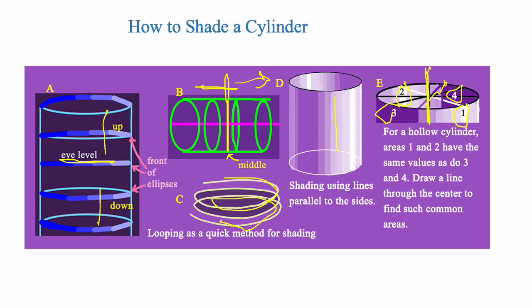To cross-hatch a cylinder, combine lines following the linear edges and curves following the round contour. They need to be relatively even and parallel to keep the cylinder from looking distorted.